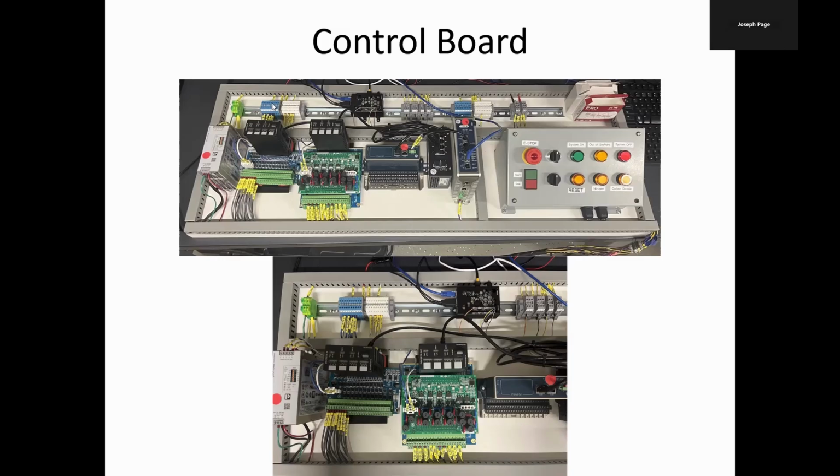We have blue terminal blocks for 24 volt positive, white terminal blocks for 24 volt 0 volt, and gray for signal. These gray terminal blocks are for the sensors in the chamber. These gray terminal blocks are for the power for the solenoids, which go to the discrete out board and are controlled by the Mark 6E controller in the HMI.